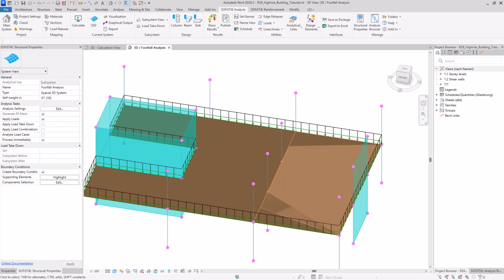For the concrete model used for the floor, the Young's modulus needs to be increased for the fact that concrete exhibits higher stiffness under small strains and short-time dynamic loading than what it's typically assumed in static design. To correct this, we will create a new Revit concrete material and assign it to the slab.